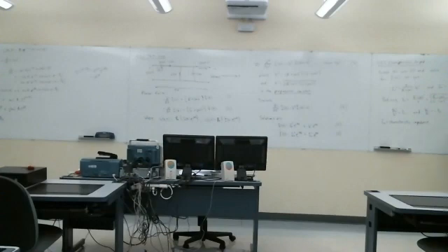And then similarly, G prime plus j omega C prime becomes 200 plus j 42,537, times 10 to the minus 6. So actually it's small compared to the R prime plus j omega L prime term because of the 10 to the minus 6 here.